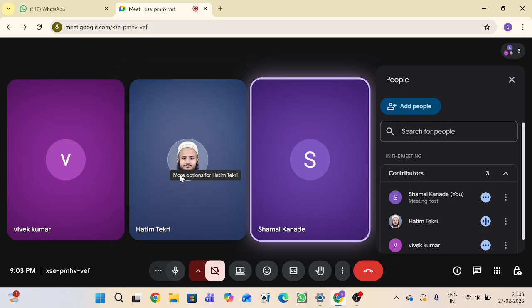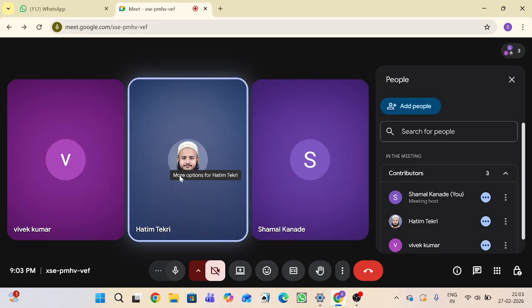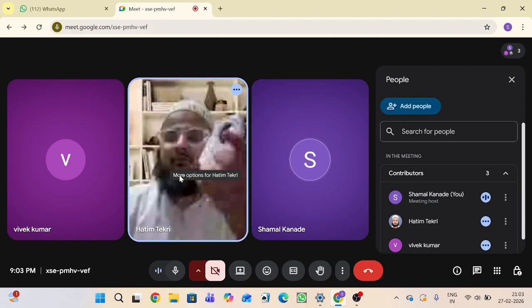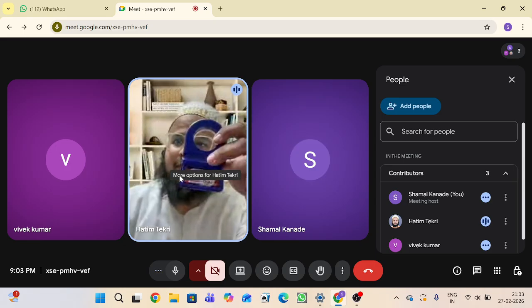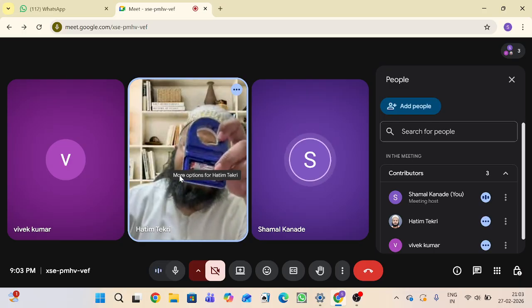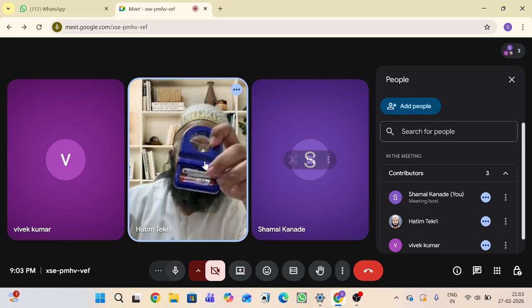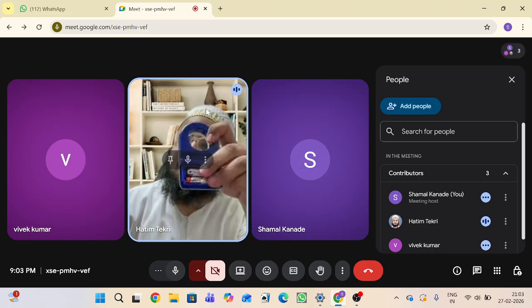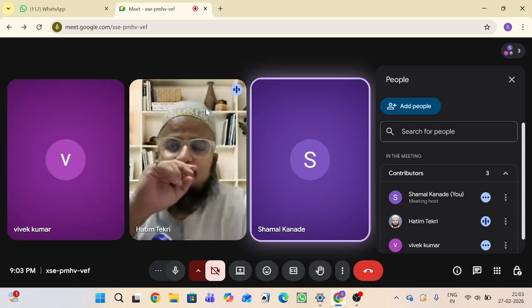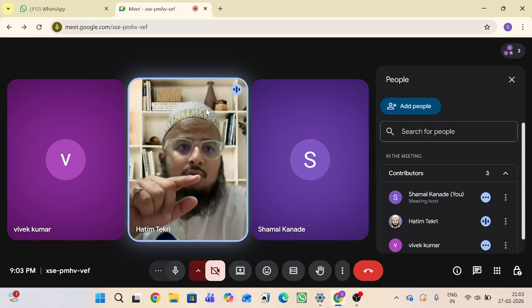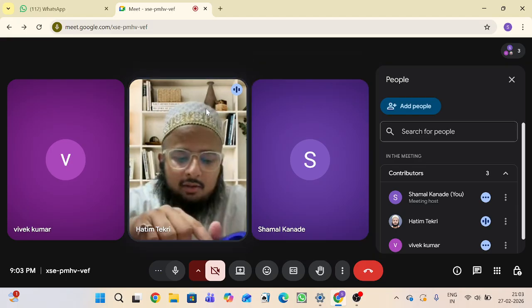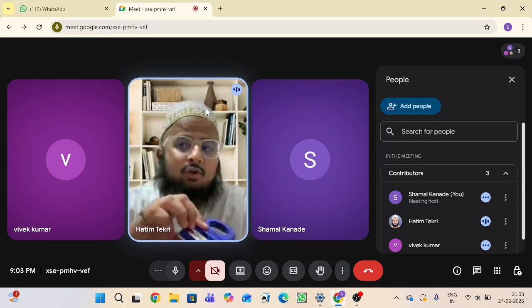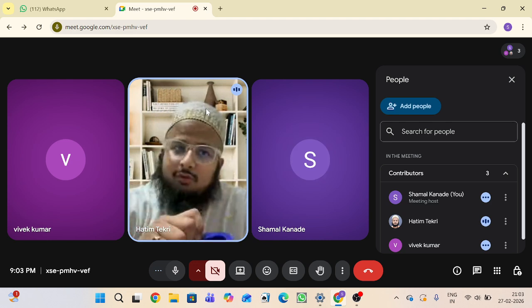Yeah, regulator. So, Shamal, I have one question. I'll show you one thing. So this is the medical device. And here they have used double A, triple A 1.5 volt batteries, two batteries, which sum up equal to 3 volt. And inside this device, they are using an STM32 microcontroller, which requires 3.3 volt.